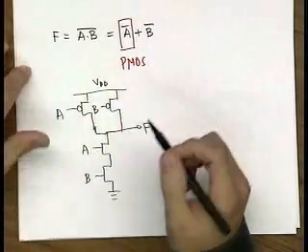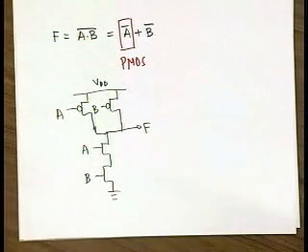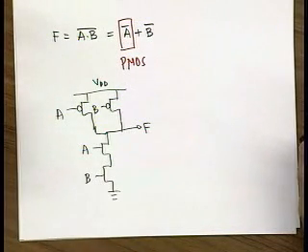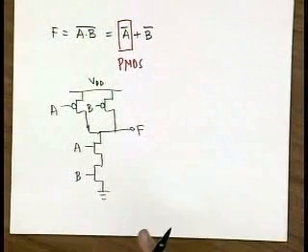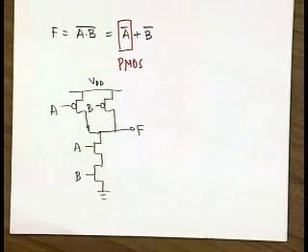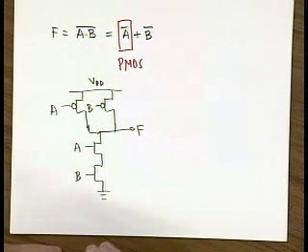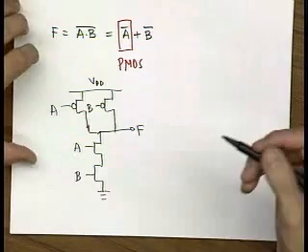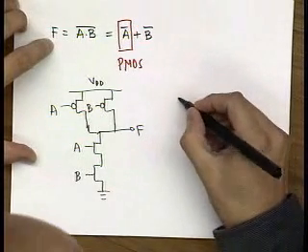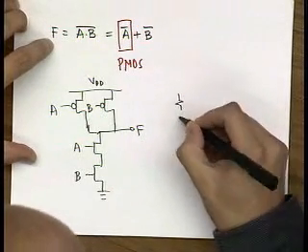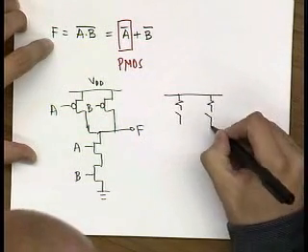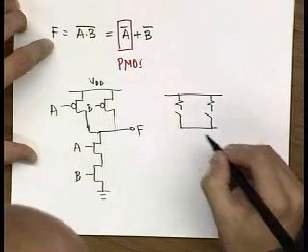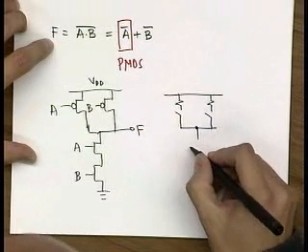So now the next question is, let's figure out the delay of this gate. How does this all work out? To calculate the delay of a gate, we can establish, the same way we did in the past for the inverter, an equivalent model of this gate using transistor models as switches in series combination with an equivalent resistance.